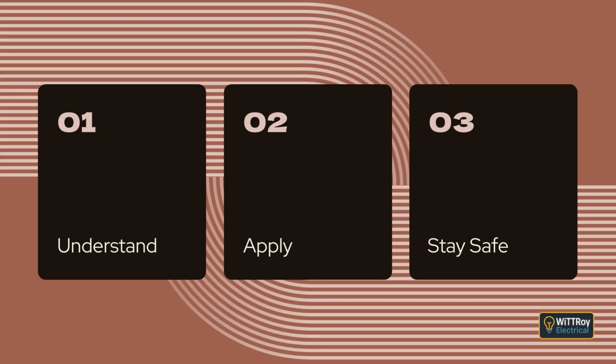Clause 2.5.5.3 Limitation of the harmful effects of a switchboard internal arcing fault. If an arc does start, protective devices must try to minimize the damage. The standard assumes that internal arcing fault current will usually be between 30% and 60% of the prospective short-circuit current. This is lower because the arc voltage reduces the current. Protection must operate quickly. It must pick up at a current less than 30% of the three-phase prospective current. There is also a calculation to find the maximum clearing time that still keeps damage acceptable.